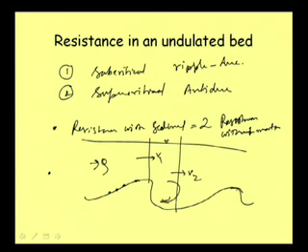Some eddies will be forming like that, and so considering all these losses, ultimately our entire resistance to the flow phenomenon will be different from the resistance of the plane form without sediment, or we can say the resistance of the rigid boundary channel. And that is the very basic need of discussing all these cases: flow in a mobile boundary channel, meaning uniform flow in a mobile boundary channel, because we are talking about the resistance flow formula, and resistance behaves in a different way in a mobile boundary channel.